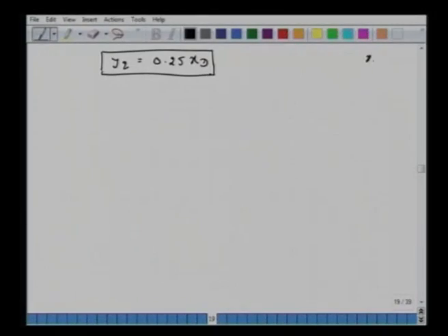All right. So here we are trying to solve analytically. Why? Because we cannot solve graphically, as the compositions are not known to us. So let's continue with this. Starting from xt, which is the same as y1 because of the total condenser, we have now connected this to y2.